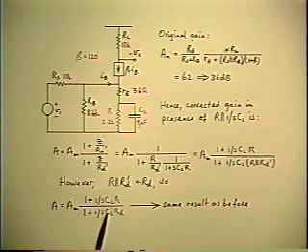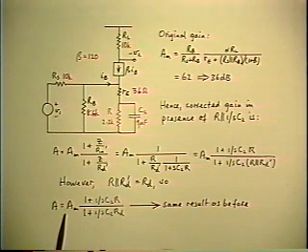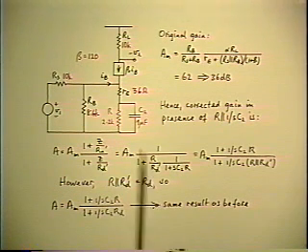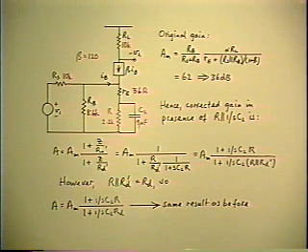So the answer comes out this time in inverted pole zero form relative to the high frequency gain asymptote. But the values of the corner frequencies are the same. They're just inverted instead of normal. So you see some more flexibility now. You can add elements in series or parallel using the theorem, and you can add any combination of elements as long as it's two-terminal. So already you can begin to see, I think, the power of this theorem. And there's a few more extensions to go yet.